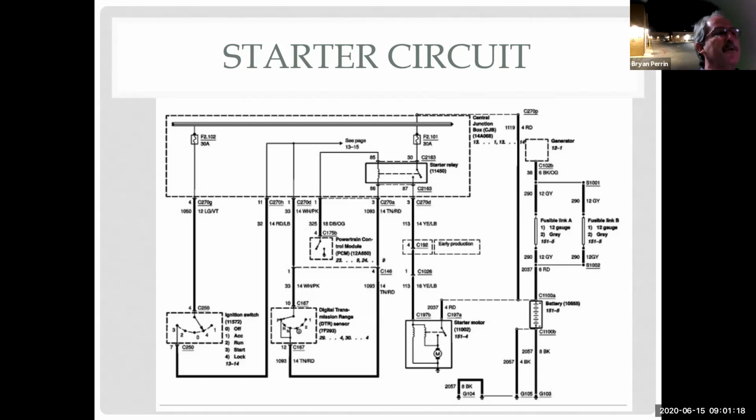So there's several reasons why the computer might not let you start the car, but say the computer lets me start it. So now I've just energized this. Now I got power going through the starter relay. Oh, and here's the load for that circuit, comes over to here. And that just activates the solenoid on the starter. So now I can close the contact here, which allows power to go through. And we're finally starting the car.